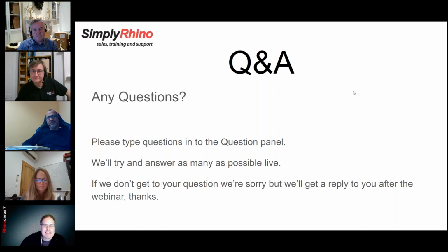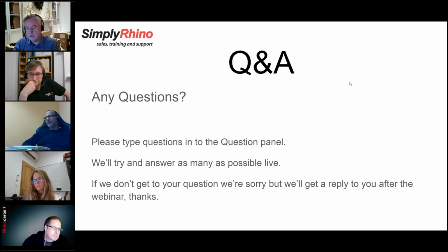Okay, I had an answer for the retopology question. I don't know how it compares to 3D Studio Max because we haven't looked at that workflow. But there are some tools available in Rhino 7 for doing retopology. The first of these is a new snap, which is persistent mesh snap. So you can turn on a persistent mesh snap for selecting points on a mesh. So if you've got a scan with, like the one Phil showed, gazillions of vertices, you can now snap to that mesh using any of the standard Rhino tools.